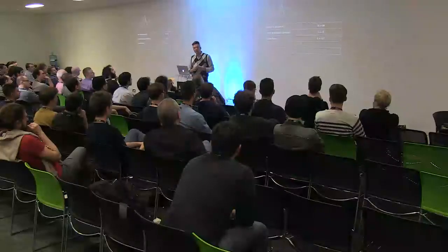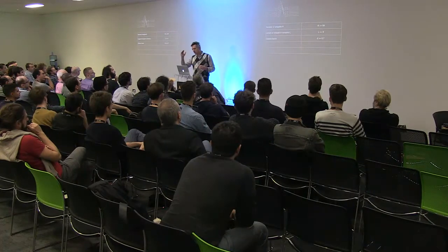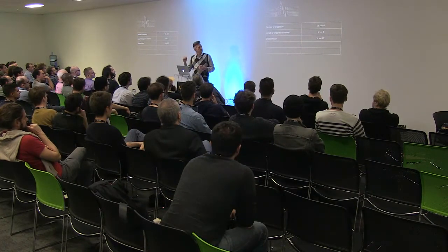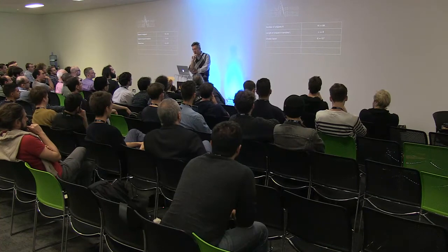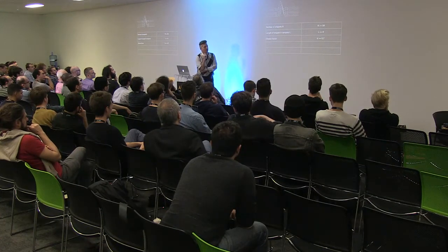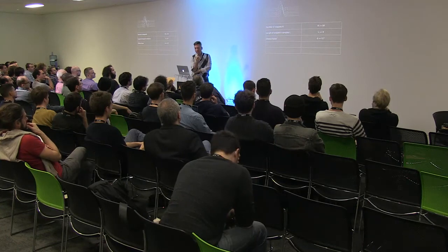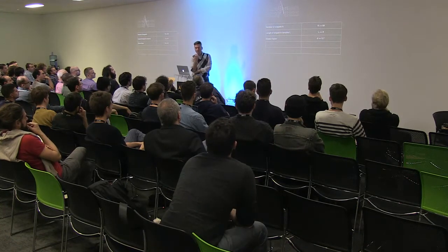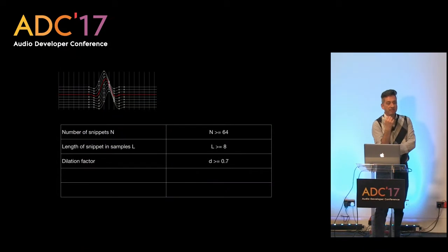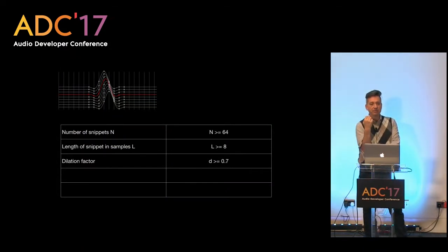The dilation is how you stretch it. If you stretch it more, you will get less high frequency content. But if you don't stretch it at all, you will get a little bit of errors in the high frequency range. It's not so very bad, this error, because this is usually followed by an integrator, which is also a kind of low-pass filter. So in this case, it works in your favor by low-pass filtering the error in the top band, which most of us don't hear anyway.